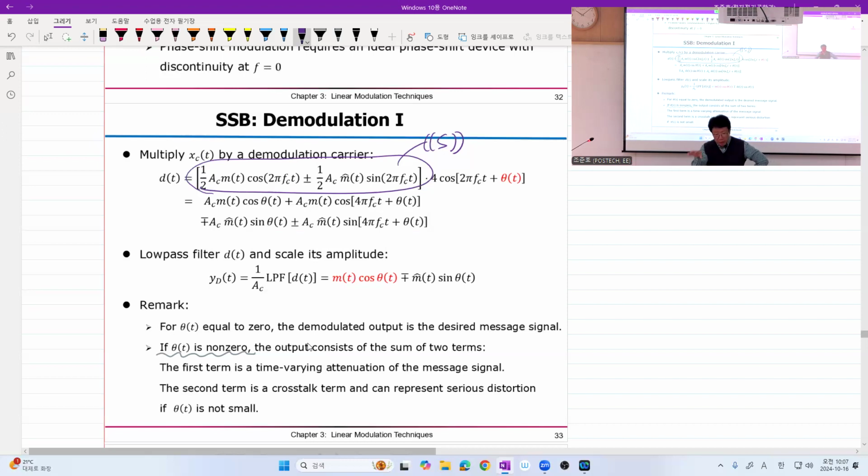Suppose you have built a 1 kilohertz oscillator. What does that mean? This single oscillation is 1 millisecond. And when you turn on the switch of the two circuits, it's not likely that your time difference is within 1 millisecond. And another one is this one. Same components, you believe, for example, 1 mega ohm, 1 kilo ohm resistor, they may have some deviation from the nominal value, your capacitor, your transistor.